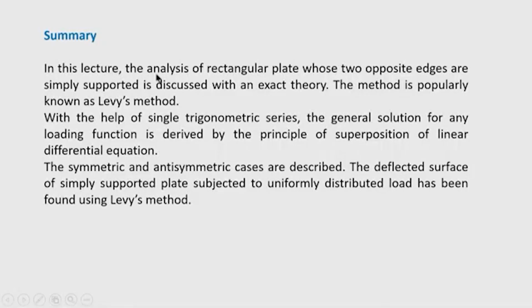In this lecture, the analysis of rectangular plate whose two opposite edges are simply supported is discussed with an exact theory, because Levy's method is an exact theory. It yields the closed form solution for the differential equation of the plate. The method is popularly known as Levy's method. With the help of single trigonometric series, because the two boundary conditions are known only, one sin function is taken in the deflected surface assumption first. So, with the help of single trigonometric series, the general solution for any loading function is derived.